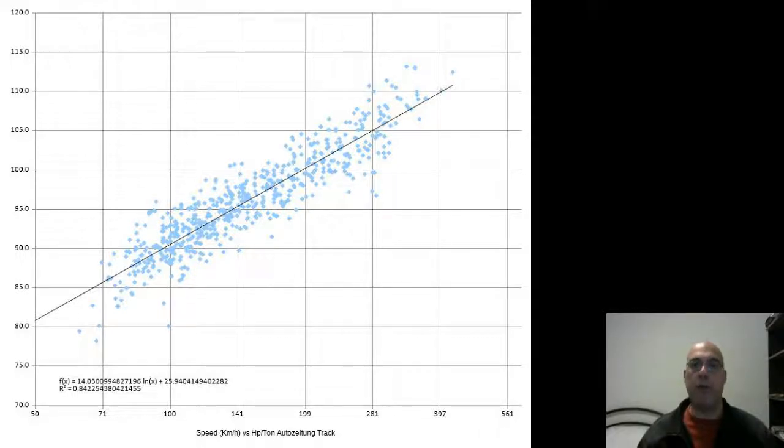So you're trying to control it with roll centers, you're trying to control it with geometry, you're trying to control it with all kinds of different techniques. But if you really want performance, you have to lower the car, stiffen the dampers, stiffen the springs, stiffen the roll bars, get rid of the weight transfer altogether, except for rallying, obviously, where you're on the